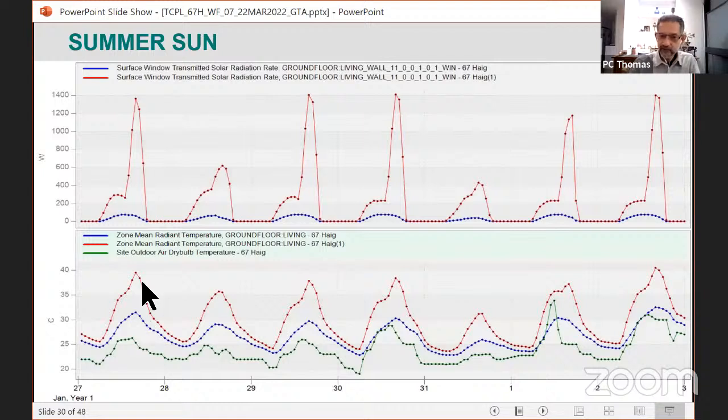So that's a benefit of 8 degrees centigrade. Now, there's no heating and cooling on this run. With that, I can look at the temperatures the same way as before, and I can take a decision that if I put some external venetian blinds, which I can control, so these are motorized venetian shades, then I may not need any additional conditioning in the house. So the decision was taken to not have any air conditioning.